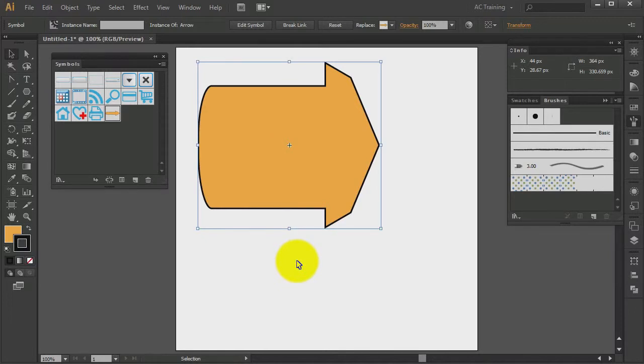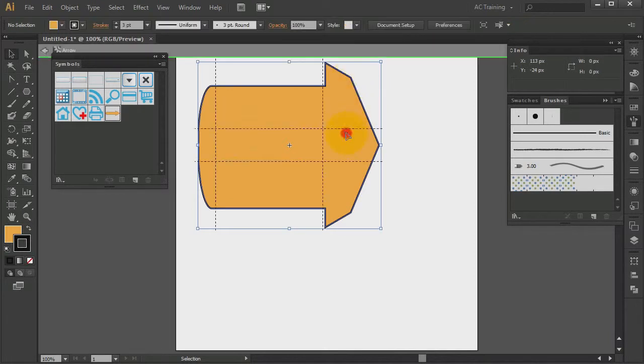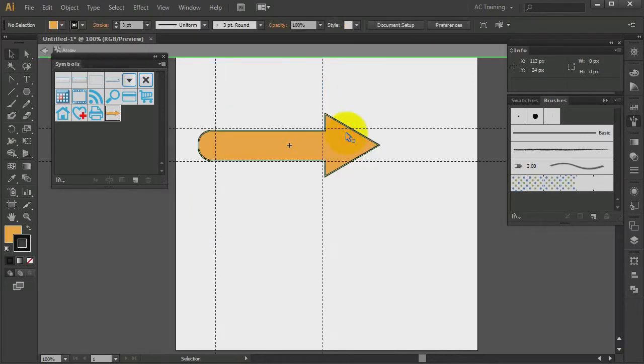There weren't any control points there, so what's causing the distortion? To find out, we'll double-click the instance to go back into Symbol Edit mode. The strange angles correspond to the two horizontal scaling guides, which were letting the middle part of the head stretch while keeping the top and bottom corners frozen. In 9-slice scaling, the corners are always kept from stretching in either direction.